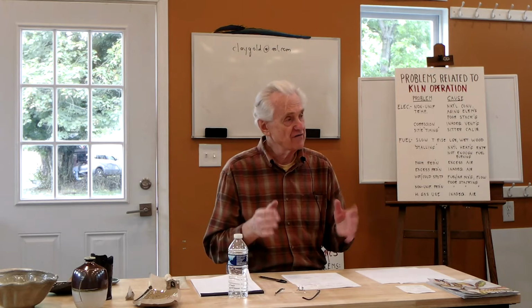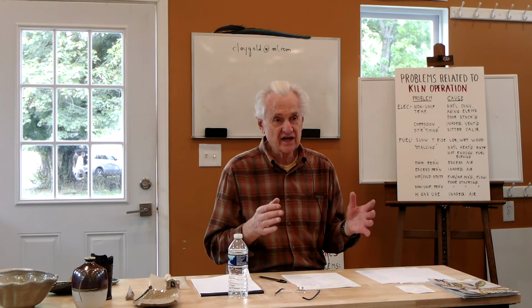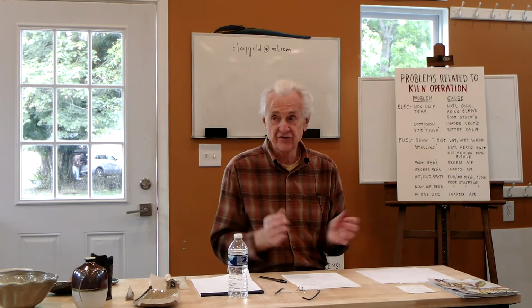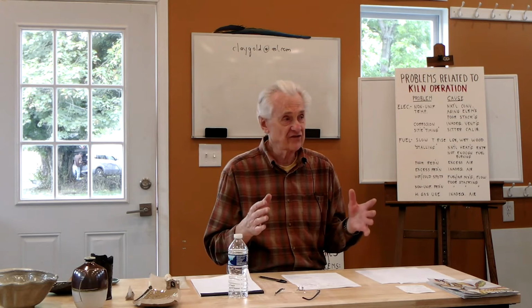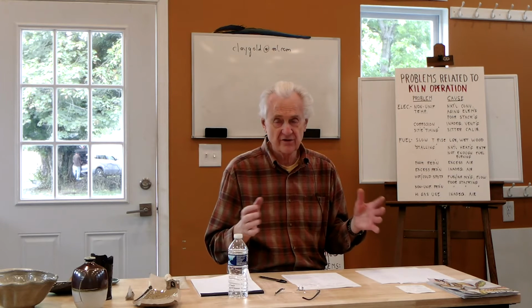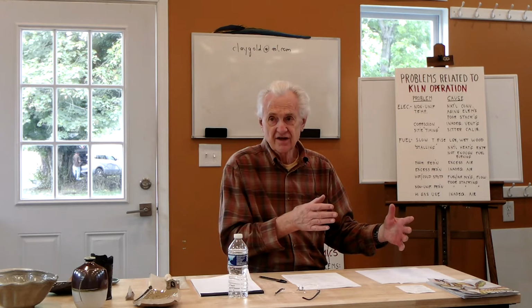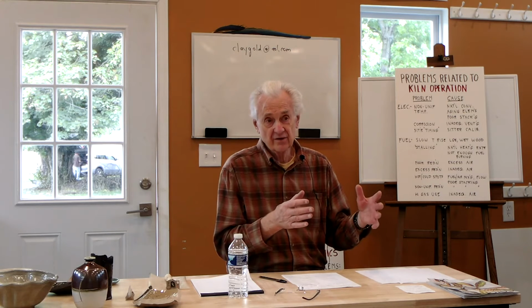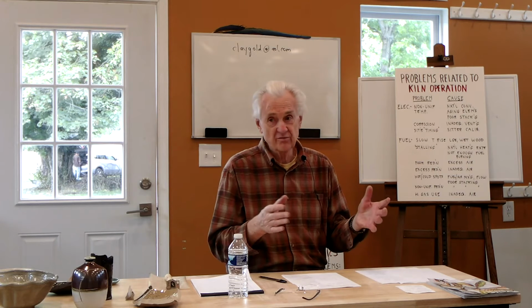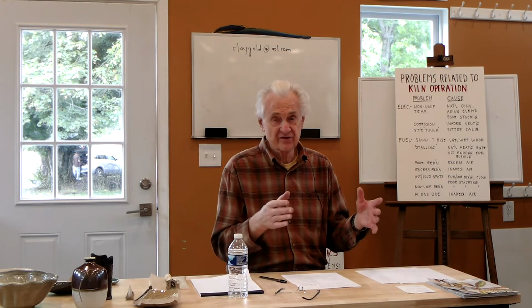If you go into too heavy reduction early on, in a gas especially, you don't want to make soot. Soot in general, soot doesn't do anything for you. It isn't contributing to the reduction. It means you've gone into too heavy reduction. And in some cases, that can actually cause defects in the pottery. One of the ones is black coring, for example, and I'll show you some example later on.